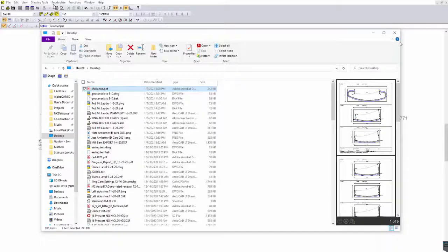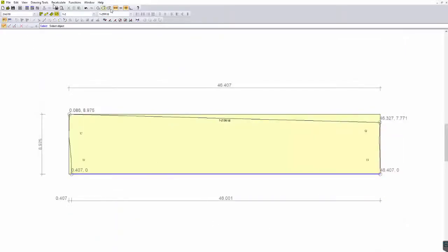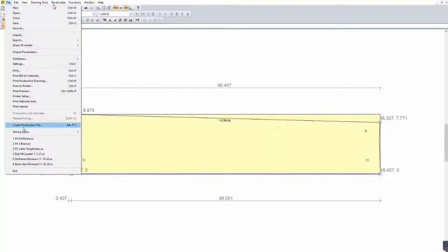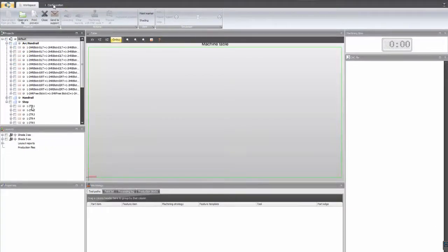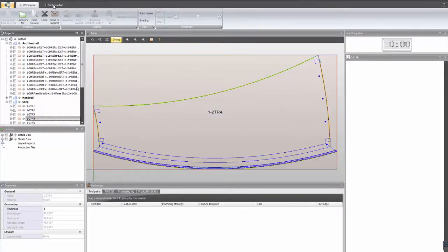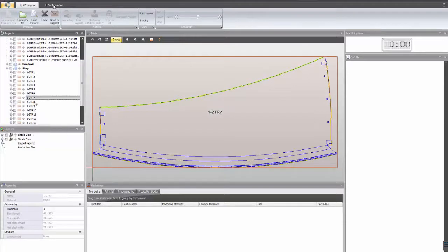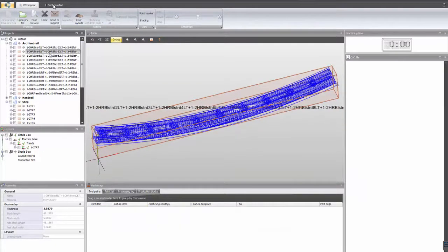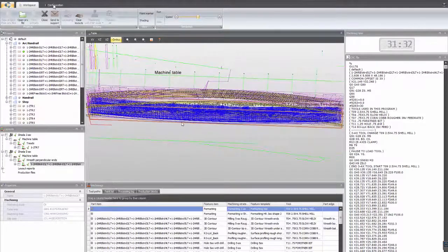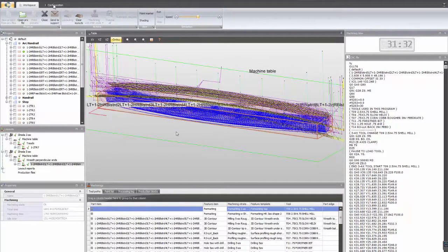And then go back into my software for Staircon and go to create production file. Here again we got wreath rail and treads. I'll just process one tread for this one just so you can see. Then go to one section of wreath here, process that, and out for production. So I mean, literally takes minutes to process the entire G-code for both treads and handrail and send it out to the floor. It's a very large time saver for us.